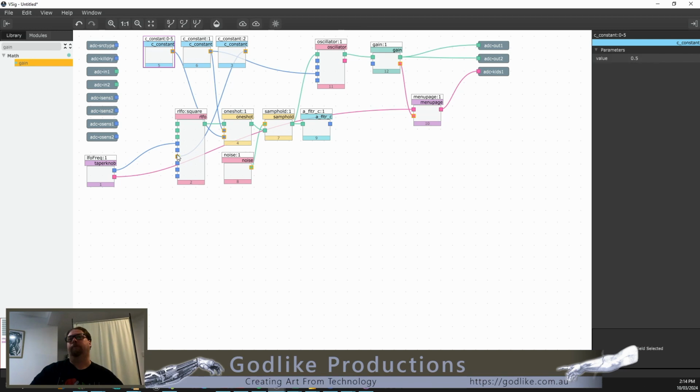So generally the way that we do this is we want to get rid of all these orange dots. So you can see these numbers down the bottom. What should happen is that they should flow from low numbers to high numbers, and sometimes this doesn't happen in feedback, but you can see that we've got a number 8 feeding a number 7. So there's a couple of ways that we can do this. The first way is you just hold down control and you go up and down, and you can put these, I generally put my constants first, or we can just drag them in here.